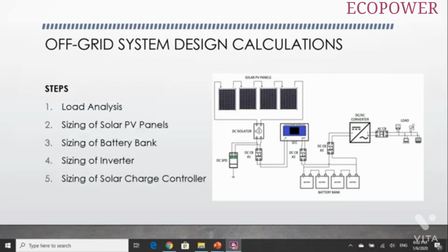Step 1, that will be the load analysis. Assuming that this installation is in a very remote area, far away from the power grid, we will take a different approach as compared to the on-grid setup load analysis, because here we don't have any monthly electricity bills where we can just easily take the monthly power consumption and divide it by 30 days. So we'll take a different approach for the load analysis for an off-grid setup.